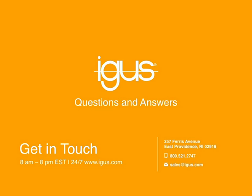Okay, another question here. Good question. What happens if the parts do get lubricated? It's generally not a problem to lubricate our parts. In fact, a lot of people who own agricultural equipment or lawn care equipment may lubricate our parts even though they don't require it. They won't hurt necessarily. We do have a list of usually petroleum-based greases or oils that are fine for our parts. But all of our lab data in the catalog is based on dry running applications.